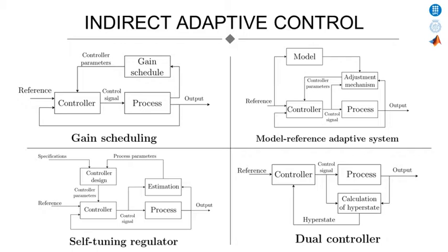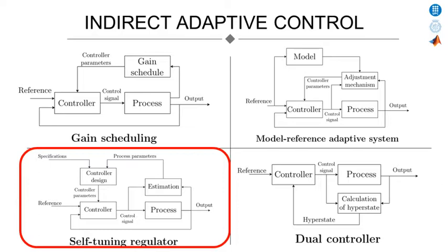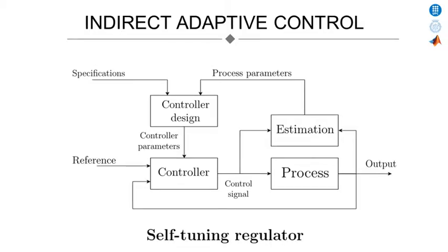Here, we can also split the problem into direct or indirect adaptive controllers. In direct adaptive control, the control parameters are directly changed without the need to estimate some other intermediate variables. In the indirect adaptive method instead, first, the process variables are estimated, and in terms of these variables the control gains are updated. As previously mentioned, in this sixth work package, we will design an indirect self-tuning regulator for velocity and position control. The estimation of the process variables will be done by the recursive least squares algorithm. The controllers have been designed by pole placement, taking the tuning equations obtained in practice 4.